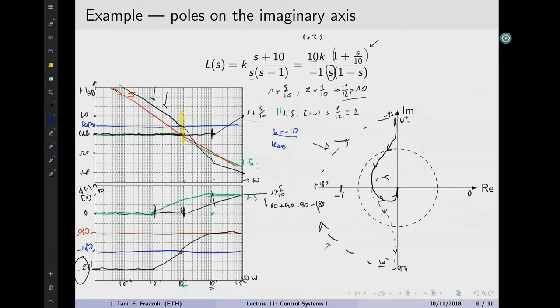So now imagine we have k that multiplies this transfer function, and k is 0. If we have 0 times something, it becomes a 0, so all this exercise collapses into a single point. So in that case, try to imagine shrinking all of this into a nice dot at 0. So where is the -1 point? Well, the -1 point would be at a long distance, right? It would be out here, correct?